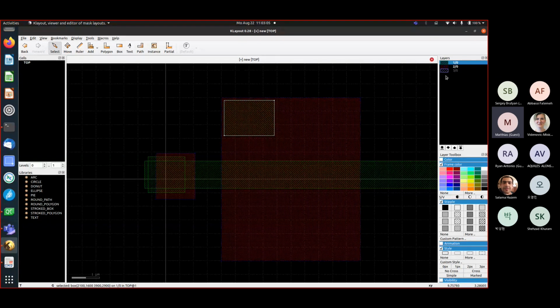So now again, I select this thing. I want to change it to this layer 3. Let's try Shift C. So you see now change to layer 3. So that's also kind of an art. People spend a lot of time setting up key bindings which are easy to use, fast to use. I think in Virtuoso there is a kind of convention what to bind to which key. Q, for example, is always to show the property dialog, things like that. So you can basically also develop your own key bindings here.